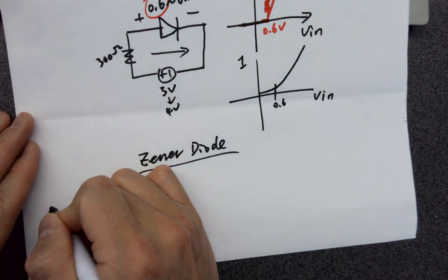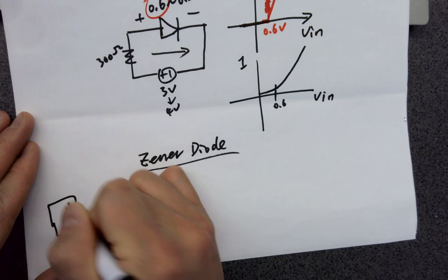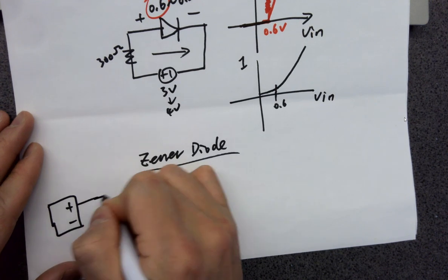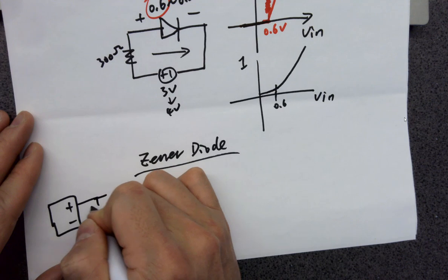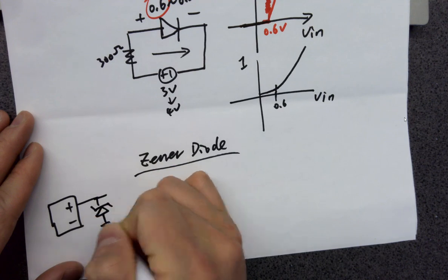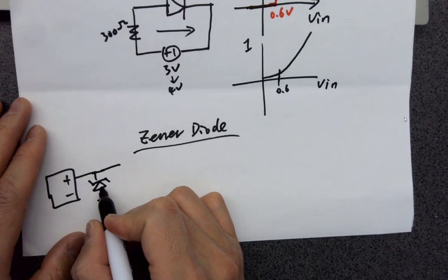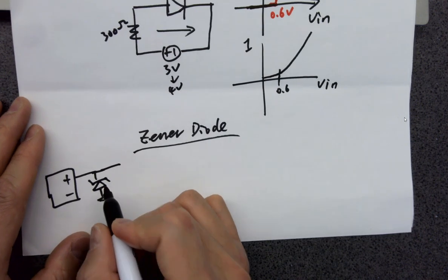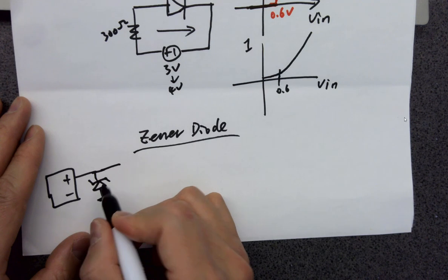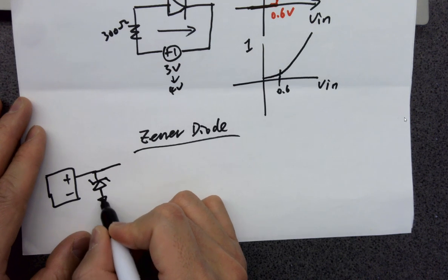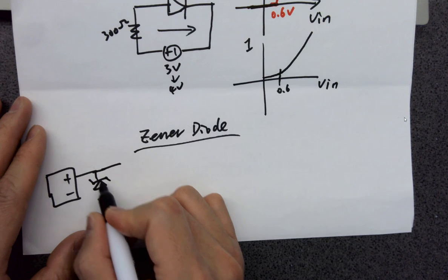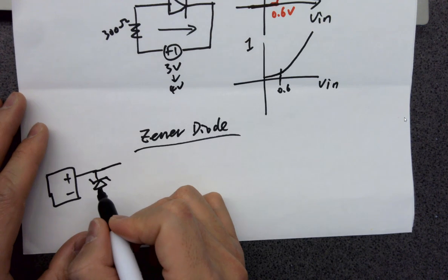So it's usually like this is a regulator, plus, minus, and just in case there's a surge. Okay. So we keep a Zener diode here, and it's being doped in a certain way that is able to allow a reverse bias, and it's going to stabilize the voltage at a certain point, depending on the concentration of the doping.